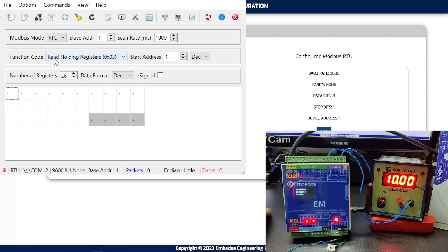So we have connected, as you can see here, the Modbus RTU terminal with an RS485 to USB converter, and then from that the data is communicated with my computer. And this is the QModMaster, wherein I'll first configure the data.